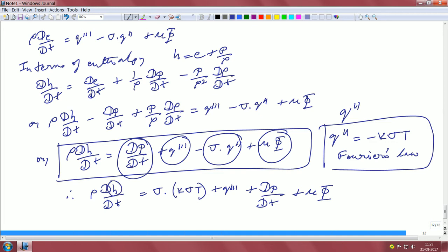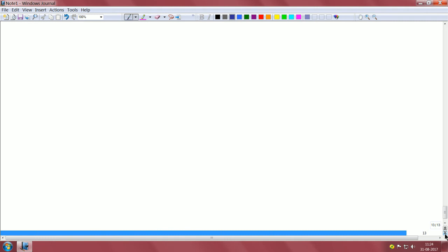We still have h hovering around, and there is T over here. Of course, these terms are still dependent on the velocity field. The velocity field is already hidden in the material derivative, because dH/dt can be expanded in full form, and the velocity components are hidden there. But still, that h needs to be cast in terms of temperature somehow, otherwise this does not make much sense, because enthalpy is not something that you can solve that easily.